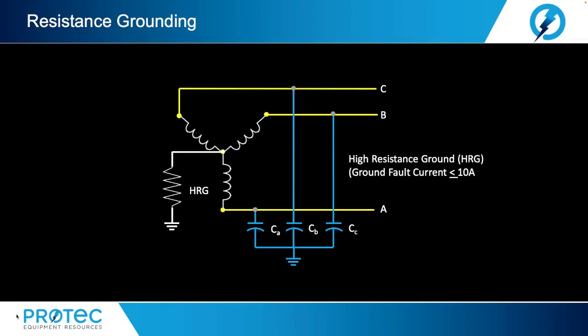This arrangement means that a certain resistance has been intentionally put between the neutral point of the system ground and earth ground. If the system does not have a neutral point, it is necessary to create one artificially. A few methods are available to accomplish this, such as a zigzag transformer or a Y-delta transformer.